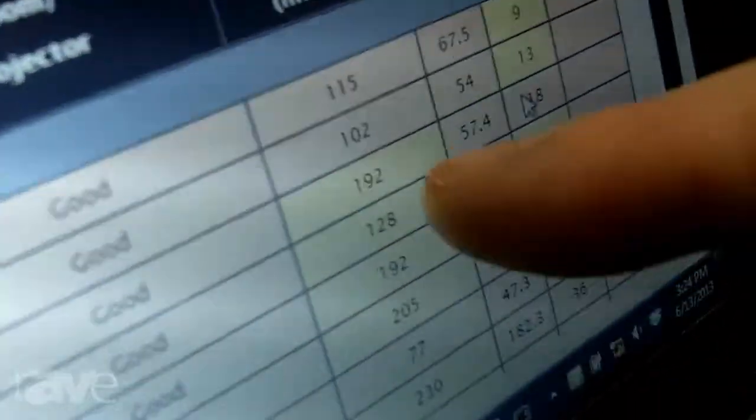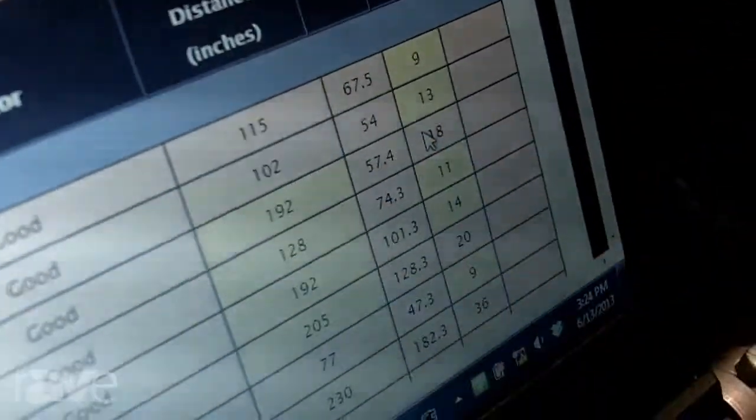And you can see over on the right where we're hitting 18:1 system contrast ratio, and if materials don't start lighting up green recommended, then it'll show you where your problem areas are. It will show in yellow where you're having problems, and it'll basically make recommendations where you have to make your changes. So this is a great tool for the designers to come in, crunch numbers, and try to add in the lighting scenario and figure out what material will work best in their application.